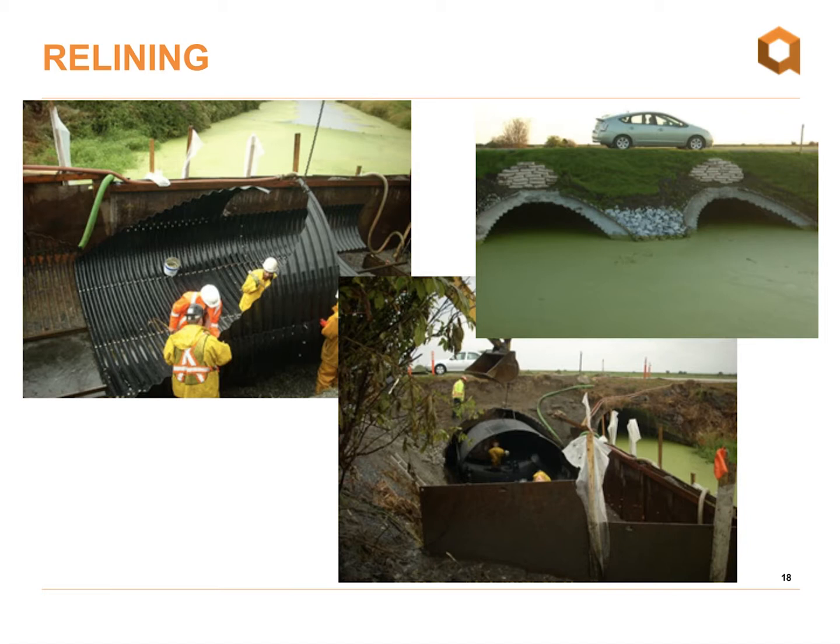That photo is actually taken from a project that we did on Hornby Road in Delta here in BC. We have a lot of organics, a very acidic environment that this was installed in. Definitely not an area where we want to see galvanized steel installed. We have a lot of coating technologies that have been developed. We have a much better understanding, and we're able to very reasonably predict the expected service life of a structure now. Knowing the pH, the chloride content, all those sorts of things, we can design for a 75 or 100-year service life.